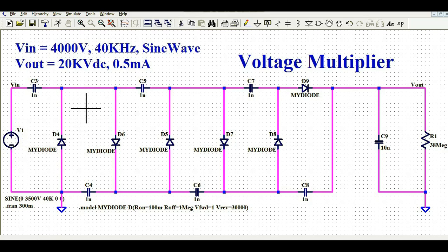From 230 volt input, you are generating 4000 volt as an output by using, let us say, flyback topology. And there, from 230 volt input to 4000 volt output, you need to use the class B isolation between the primary and secondary.